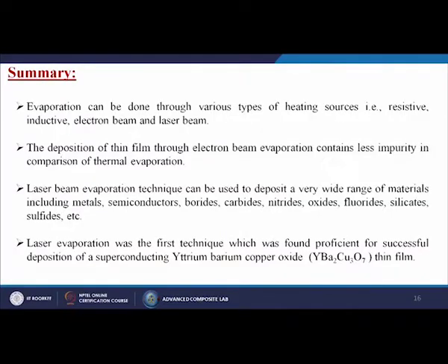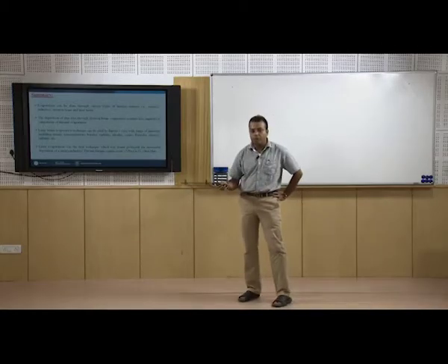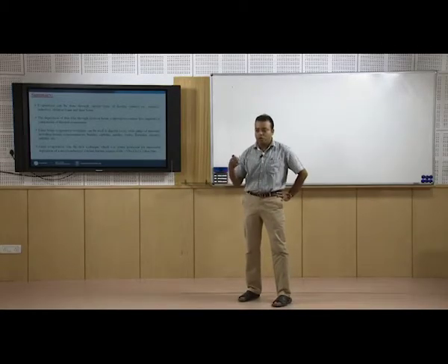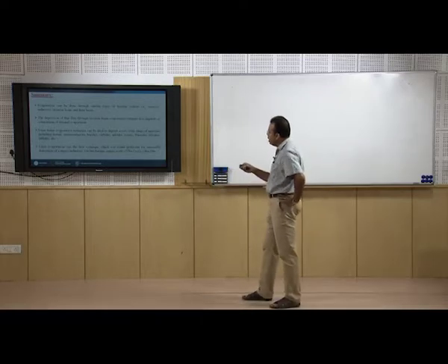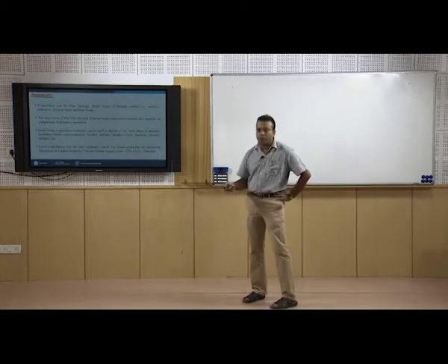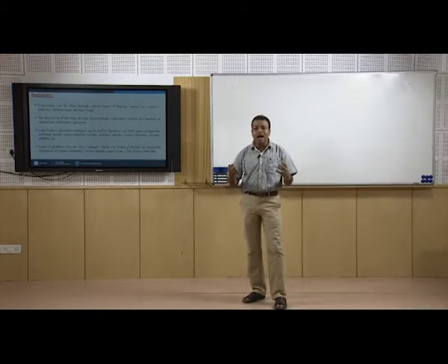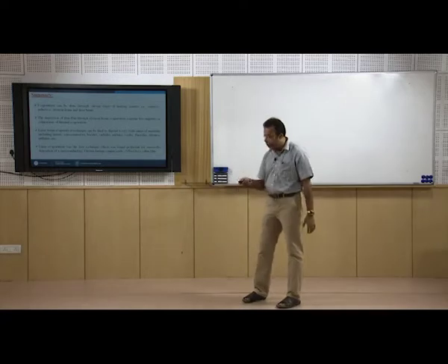Laser evaporation was the first technique found proficient for successful deposition of a superconducting yttrium barium copper oxide thin film. This is also one kind of very wonderful, fantastic material. It is not possible by any of the other three methods like resistive, inductive or electron beam, only by laser evaporation, because it needs high energy to evaporate.